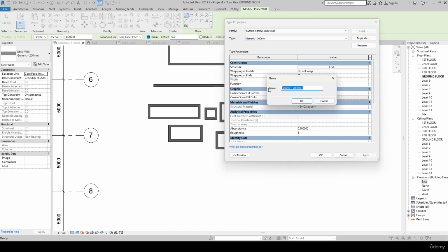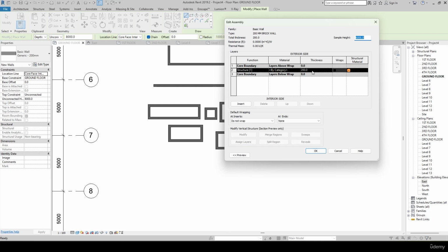I want to create a 200 mm wall, maybe say I'll call it the brick wall. Okay, I'm selecting the brick wall. Now the brick wall duplicate has been done. Now I want to add the values as well. Here the value 200 is fine. Now the material, which material you want to assign, you have the option here. Here you will find the material selection section.